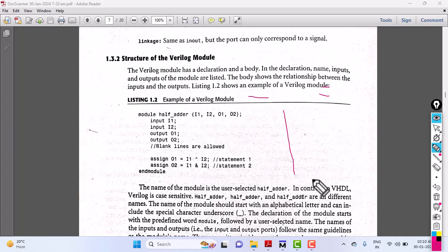Have all understood the first part now, the structure of the Verilog program? This structure is similar for any design you take, from a simple gate to a complex design; the structure remains the same. You should start with a module. This is a standard word. Module name, you can give any name, but it should reflect your design. And within the bracket, you are defining what is input and output for your system.